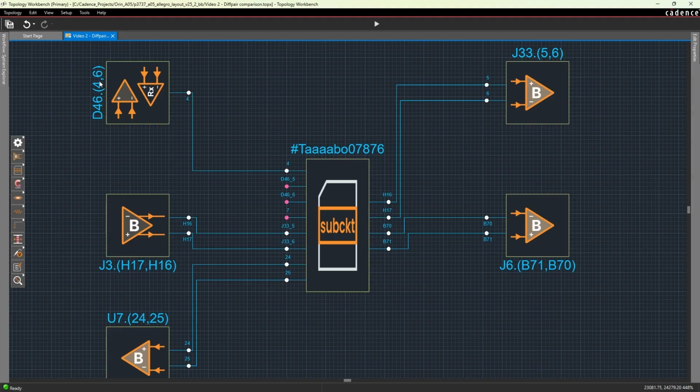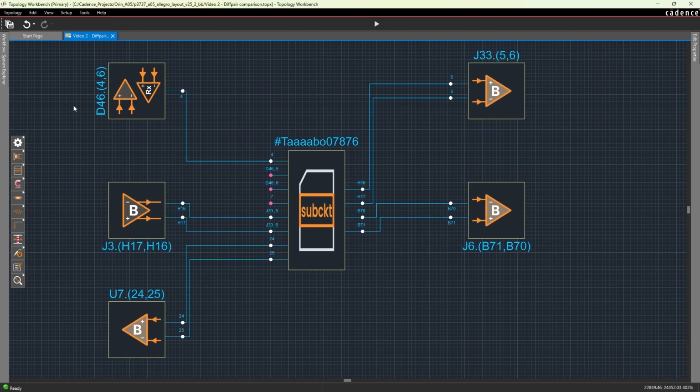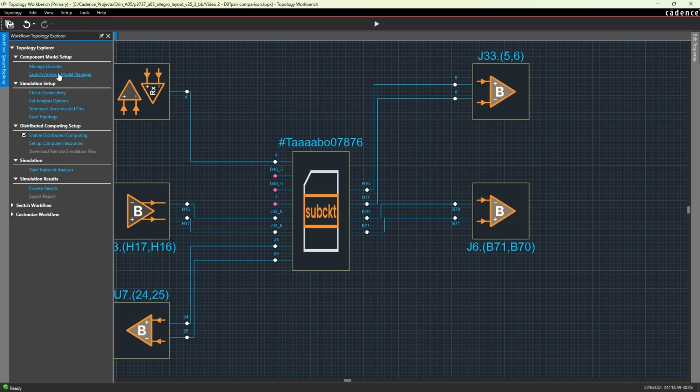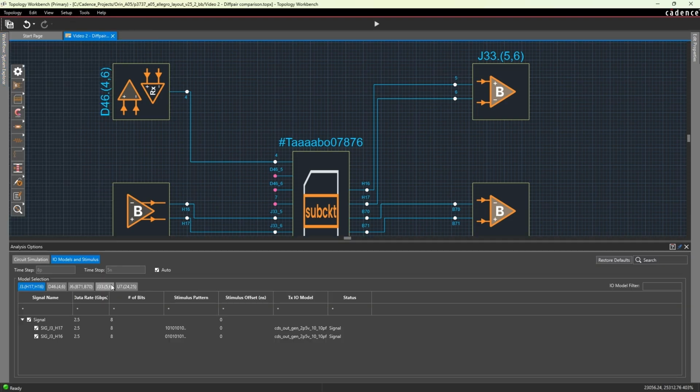Now, what I like doing is testing different signal frequencies. Some of these will fail certain frequencies depending on how they're routed and what they are for. So that's exactly what we go to test. Not all routing paths are created equal. So what we're going to do is set up our analysis options and then see how they perform in comparison to each other. We'll start off with 1 gigahertz for signal injection, and then we will do the simulation.